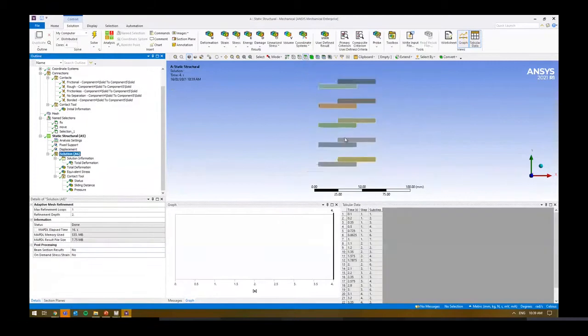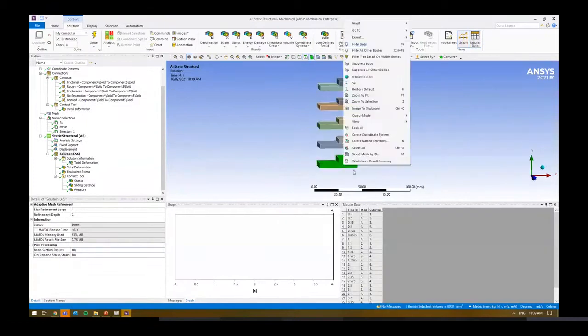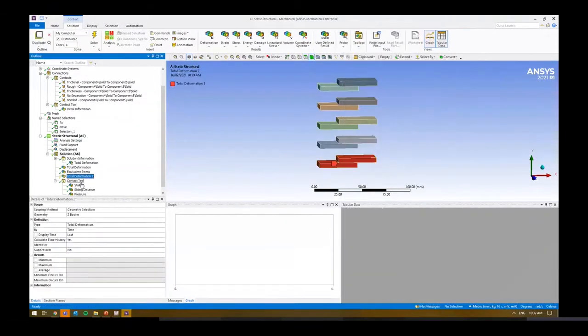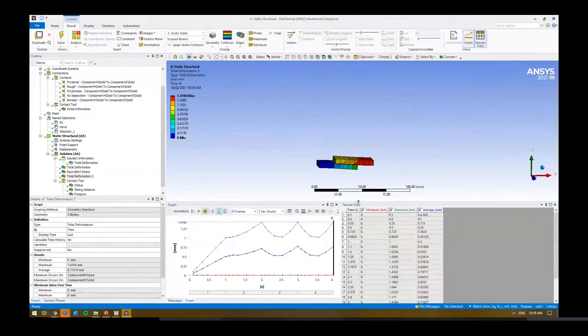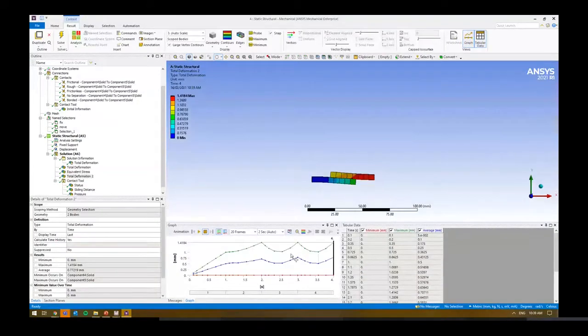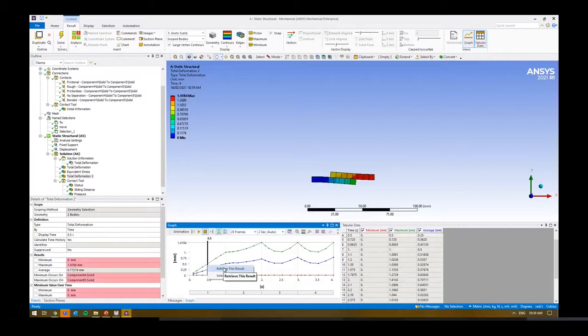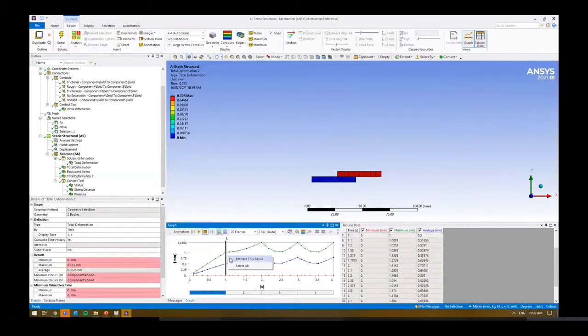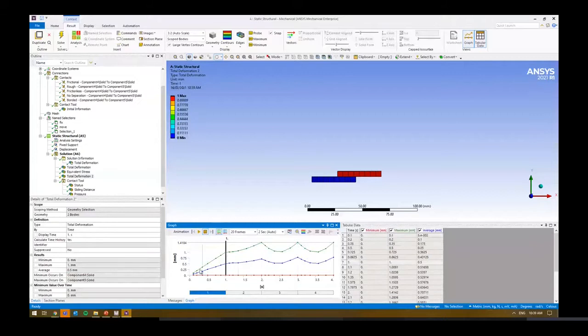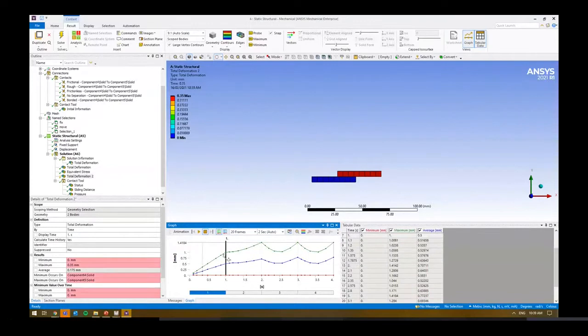So let's just focus on the block here for a second. We can insert deformation just on that block. I can hit the play button and it'll go through that process. You'll also notice straight away I've got a bunch of these dots. Each of these dots is one of those steps, those equilibrium steps. Remember, I'm not applying the full load. I'm applying a small section, looking at the stress results, then applying another section, looking at the stress results, and building it all the way